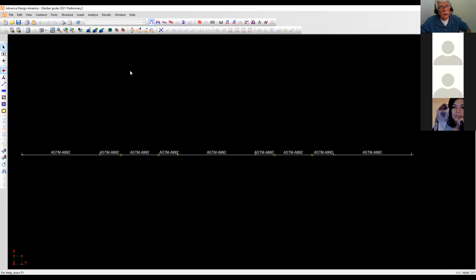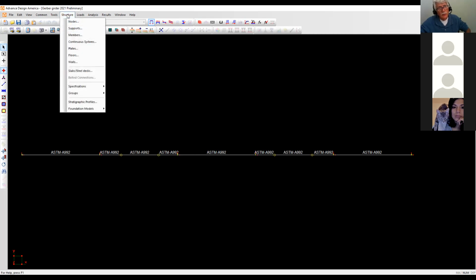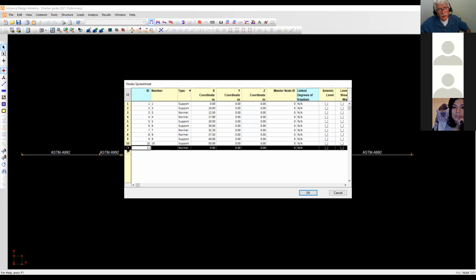Then the first thing you do is up here under structures. I'm pointing at the structures. You click on structures, and this is where you start inputting. So the first thing you do is you go to nodes, and of course you click on this plus sign here, and it keeps adding. You start plus, plus, plus, plus, plus. In other words, you do it at least 10 times.